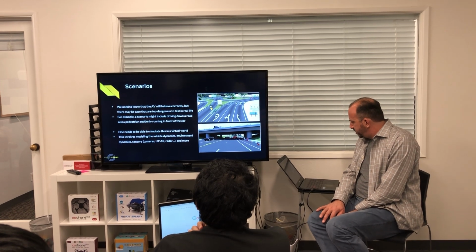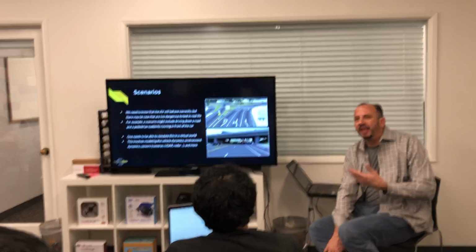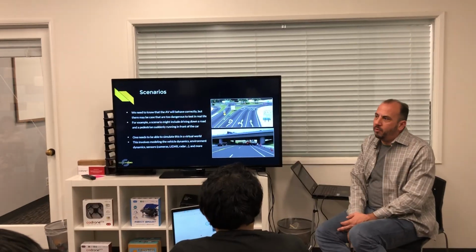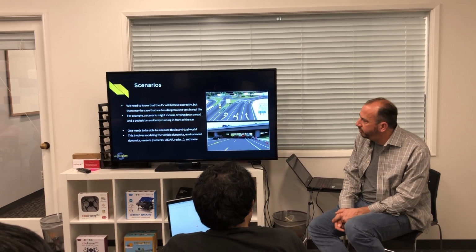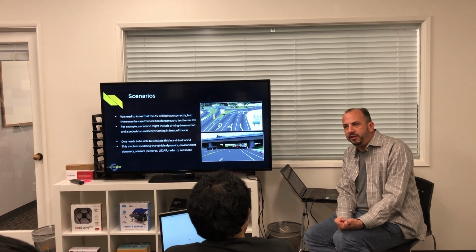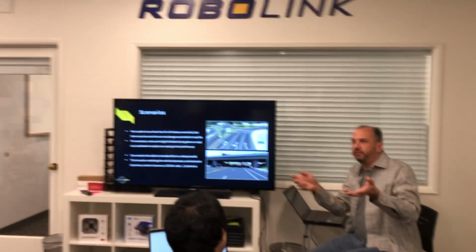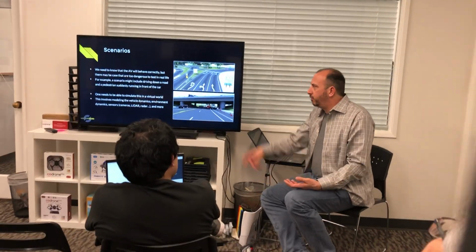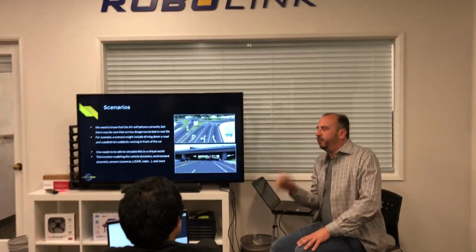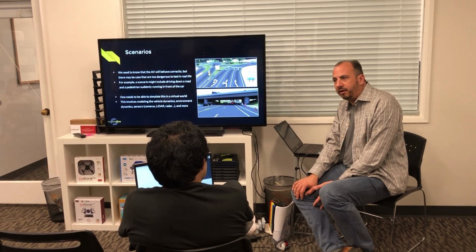Yeah, I think I mentioned this. To do a simulation, there are all these different levels of detail you may want to get into if you're simulating your vehicle. You may want to do a full end-to-end simulation where you're simulating the visual scene that the car sees, rendering a synthetic image like this. Maybe you render one, maybe you're simulating a car with 4 cameras. We would have to simulate 4 images and feed them into the car. We would also have to simulate things like the LiDAR sensors, the laser sensors, the radar.